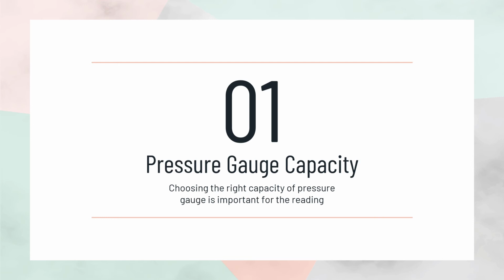However, after a manual calculation, the pressure turned out to be no more than 100 Pa. Therefore, our pressure gauge capacity is too big to measure our system.